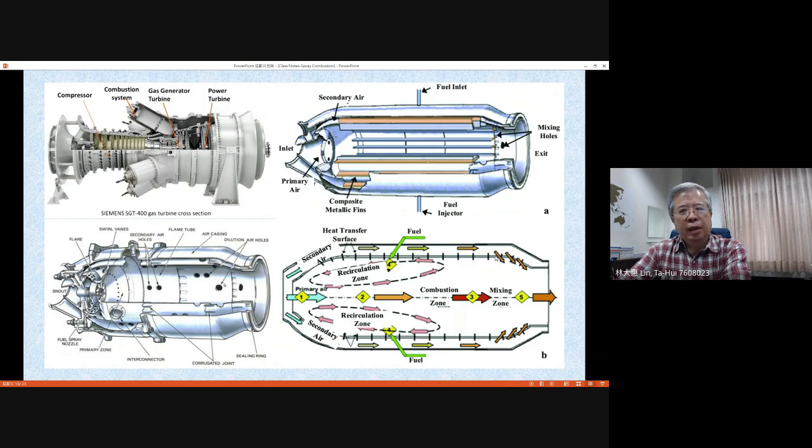Later on those products will mix together. Finally, there is some air, as I mentioned earlier, the so-called secondary air. It moves around the ends of the combustor, flows into the combustion chamber and mixes with the products together, then goes downstream to push the turbine to rotate, and later on they will generate electricity. And this kind of design on the recirculation of your airflow with the liquid fuel is basically a good design to prevent thermal NOx formation.